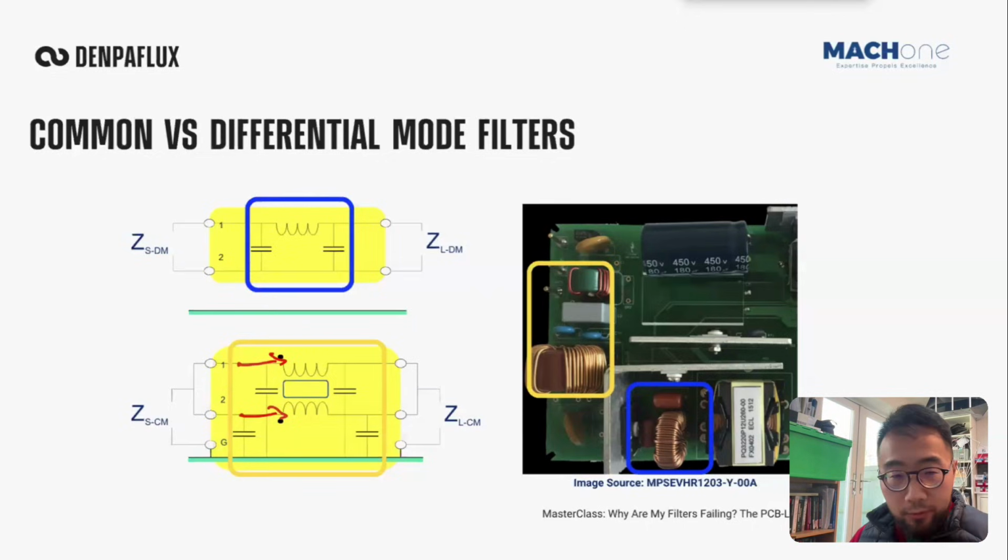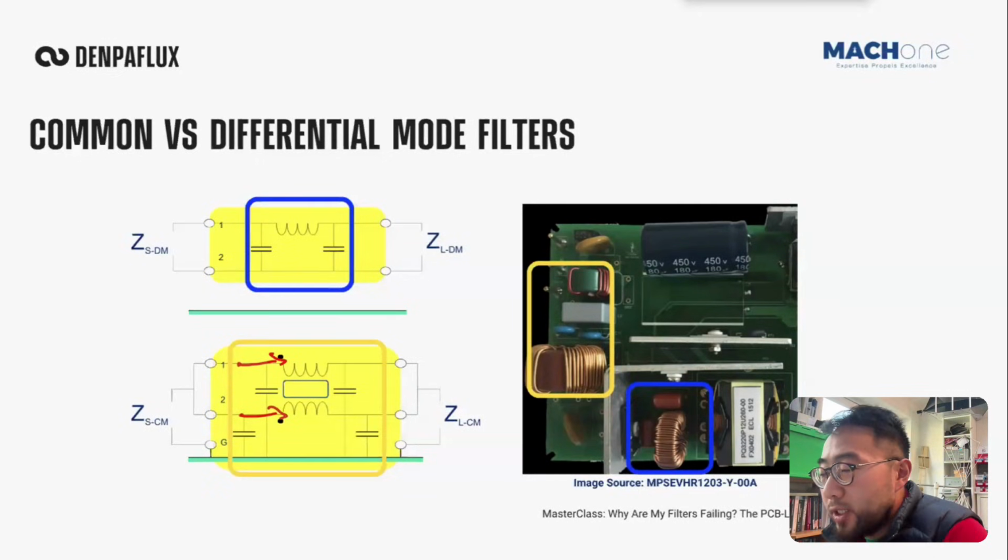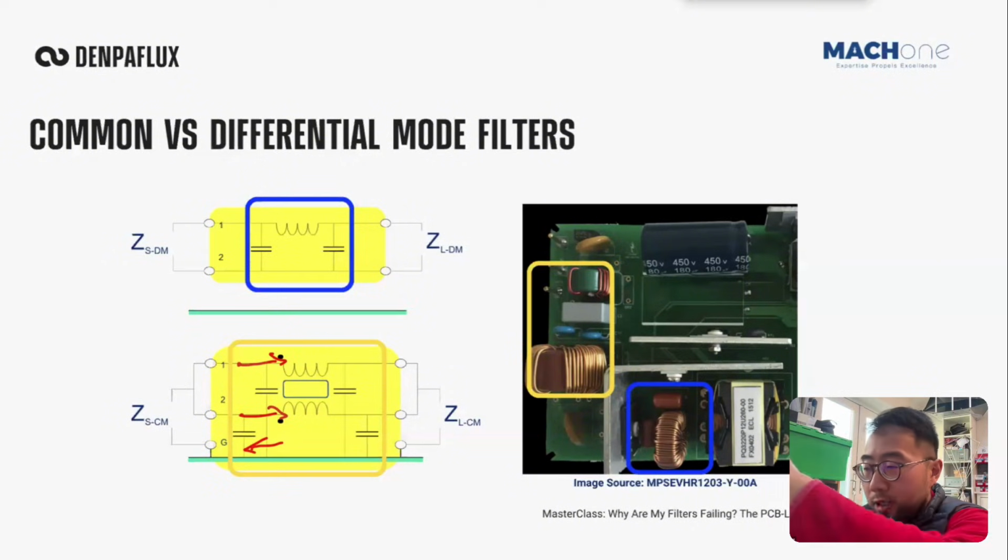Whereas if you look from the field perspective, you have a field that propagates from the source to the load at approximately close to the speed of light. And the current is just a byproduct. It's a trailing current behind the wavefront. Then you will understand, right? You can cause common mode current to flow, most of the time on the surface of the conductors. And then the return path would be either a chassis or earth or some cable nearby, right? So that's basically what we mean by common mode against differential mode.